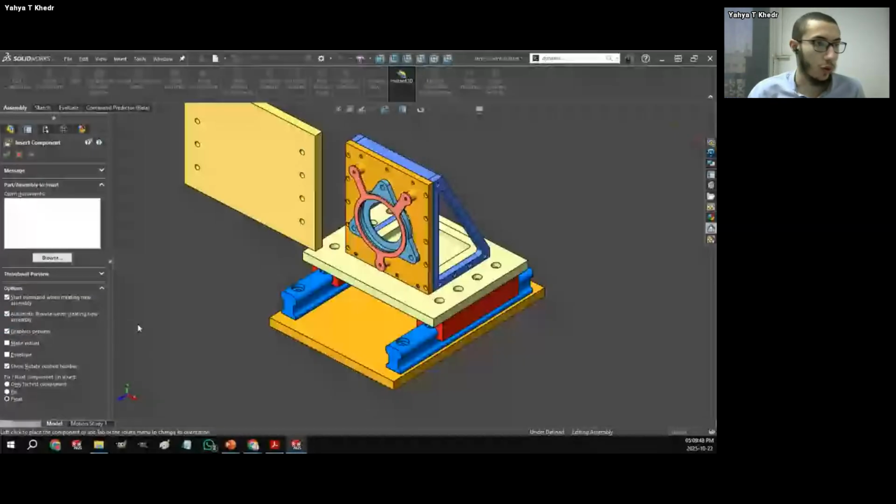Let me know if you know what I'm talking about down in the chat, because once again, it's very easy to modify every single component you add, but what's even easier is to change the setting once, and then everything is already floated as soon as you add it inside of SOLIDWORKS. It's going to save you a lot of time when you see how many components you're going to add throughout your career. So let's see, has anyone noticed it yet?